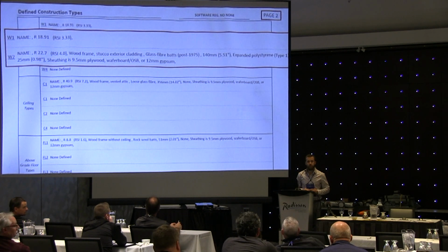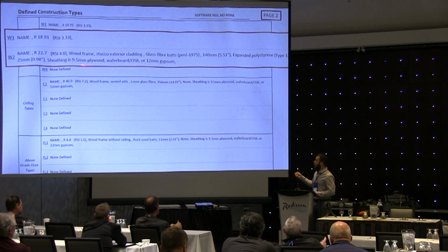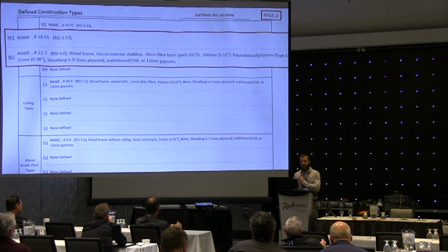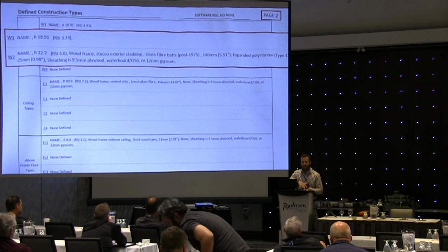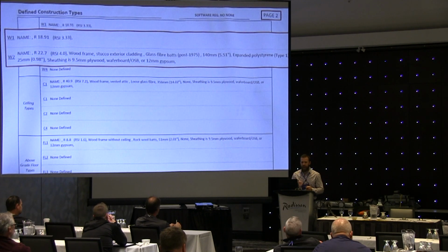Yes? Take into account sloped ceilings. Yeah, so sloped ceilings are relevant for exposed area, right? That's what you mean? Like a cathedral ceiling? Yes. Yeah. So the difference there is going to be, the R value would be very similar. We actually don't, in this software, worry about heel heights and the compressed insulation on a sloped ceiling or on an attic. CSA doesn't go that intricate.